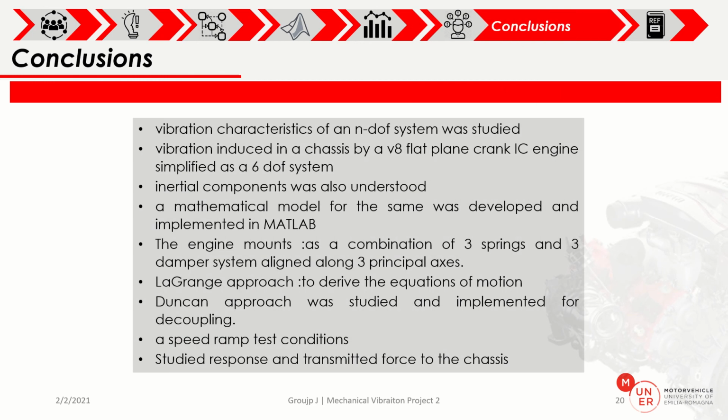And then the conclusion. Through this project, we have understood and studied the vibration induced by a V8 flat plane crank internal combustion engine, simplified as a 6 degrees of freedom system. A Lagrangian approach was carried out along with a Duncan approach in order to study the response of the entire system and the forces transmitted to the chassis. We implemented all these things in MATLAB considering a speed ramp test condition from 0 to 10,000 RPM.